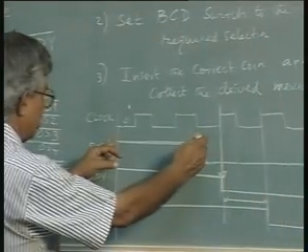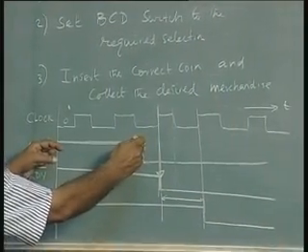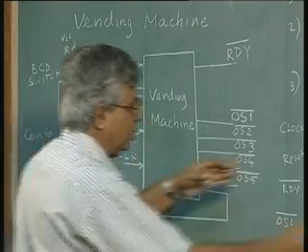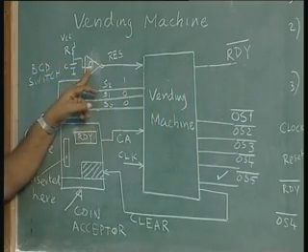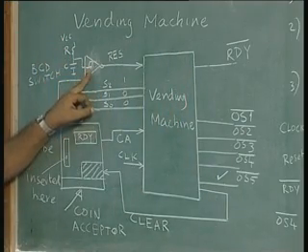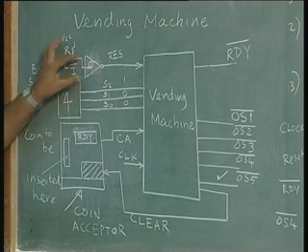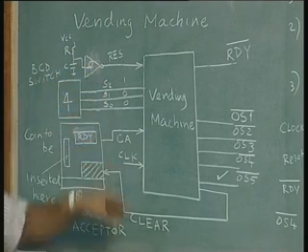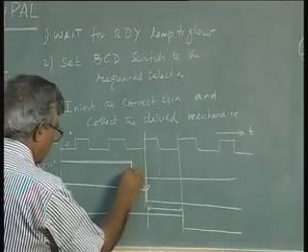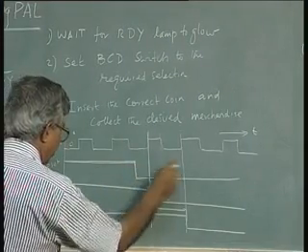As the power is on, the reset will be high, but once the capacitor has reached the threshold value of the inverting Schmitt trigger, the output becomes low, so reset will be low, and that is where normal functioning begins.